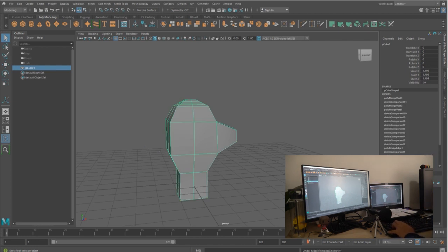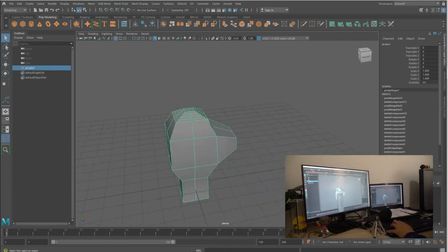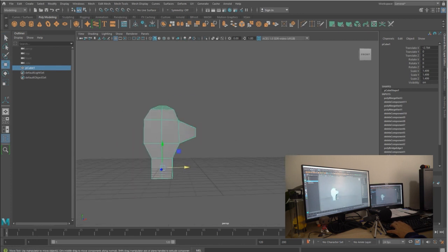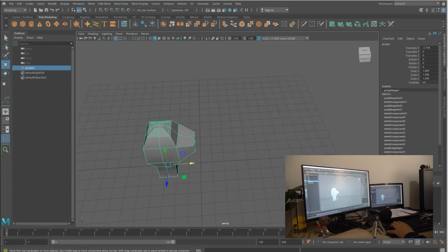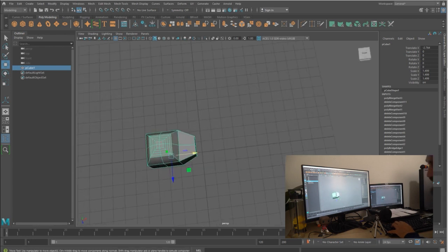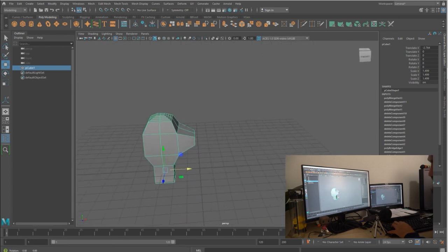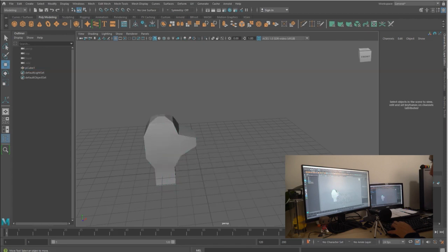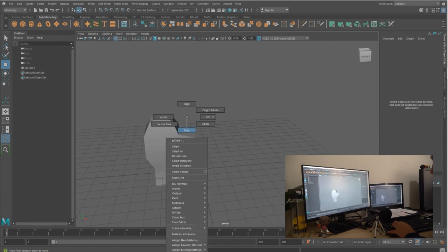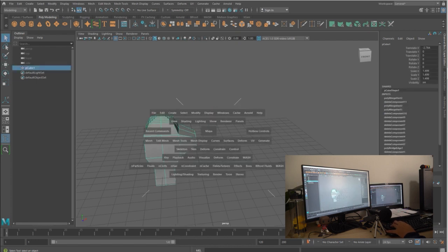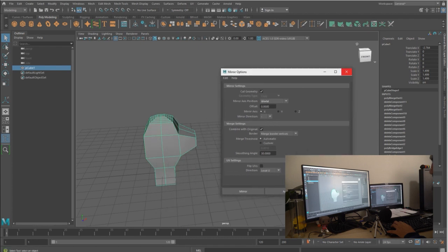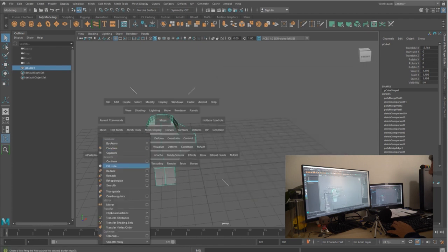Maybe you want to mirror in another axis. So you're here, you want this to be the same as this one, so you go here. I move it a bit on the side, so it's not in the middle but a bit offset from the center of the world. We go space, mesh, and mirror. We can go in the little box, so I do it again here.